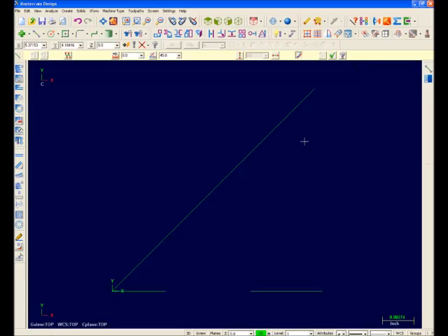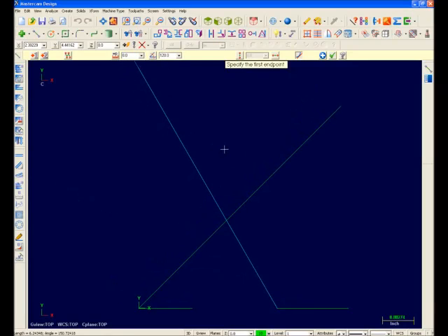To illustrate the flexibility of Mastercam X, I'll create the 120 degree line by sketching its start and end point and then entering the proper length and angle. So I'll go ahead and select this end point here and stretch it somewhere out on the screen and click. I'll select 8 inches from the drop down in the function ribbon bar. Notice how your inputs are remembered. I'll then type 120 degrees and hit enter. My live entity display updated. It looks good, so we can apply.